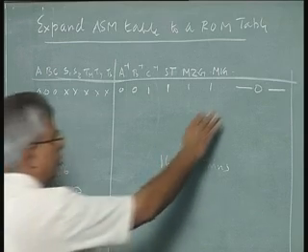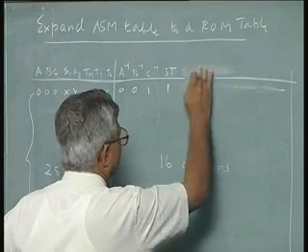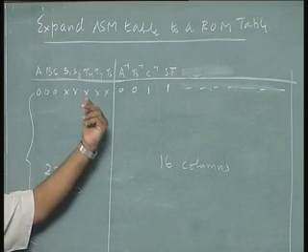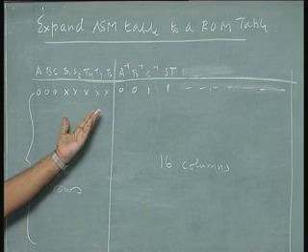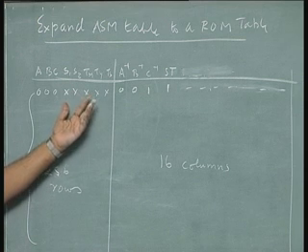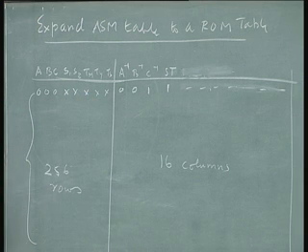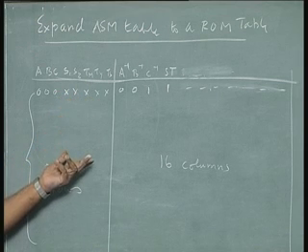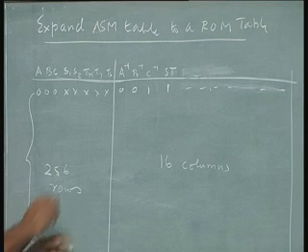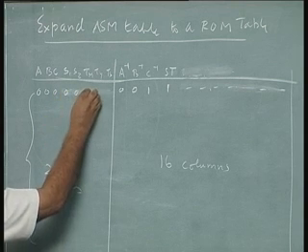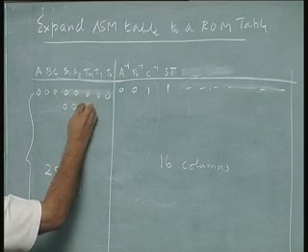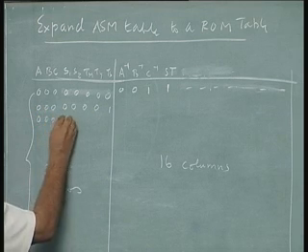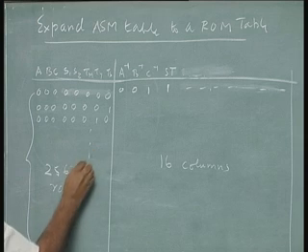So, I am not going to fill this one like an example. Now, this XXX will not hold in a ROM table. In the ASM table, I can have an XXX because I am only looking at the conditions for next transition. Now, these 5 X's have to be expanded into 32 rows for 5 inputs. So, I will have to start with 0 0 0 0 0, 0 0 0 0 1, and so on, for 32 rows.